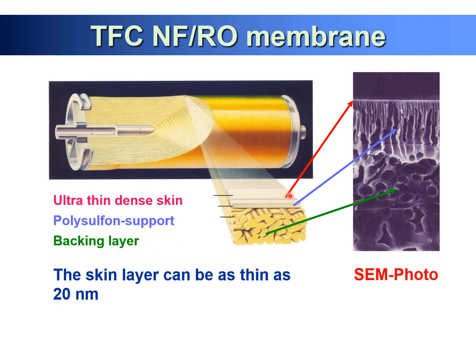So this skin layer, polyamide, can separate your salt and pure water. The pore size is almost 0.6 nanometer, and water molecules will pass through, and then you can separate your salt and pure water. So this skin layer is very important.